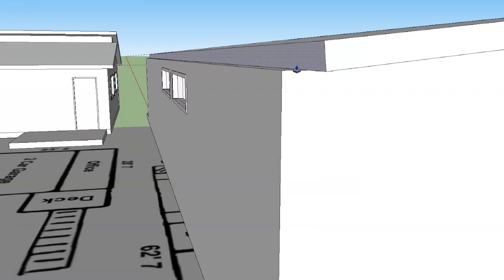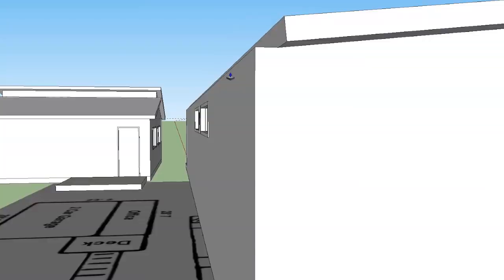This part of the wall right here, I pull it out 9 inches. Look at what it's doing. It's intersecting with the rest of this wall because of that slope. 8 feet doesn't mean 8 feet on the exterior part of the wall because of that slope. This is where roofing gets really kind of complicated. So we're just going to go ahead and we need to actually pull it out a little bit more, make it flush, and then go another 9 inches.